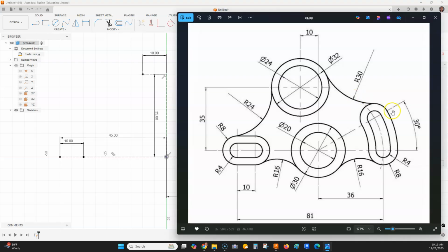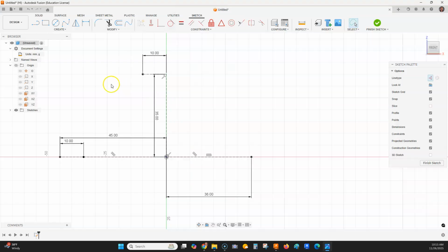Our next construction line we want to draw is this one that says 30 degrees. I want you to notice that this line comes way out here. It doesn't really snap any place. All we're trying to get is just a perfect construction line here that is 30 degrees from the first line that we drew. Let's grab a hold of the line and go down to our origin. As I drag out, I'm just going to come way out here. It does not really matter the distance.